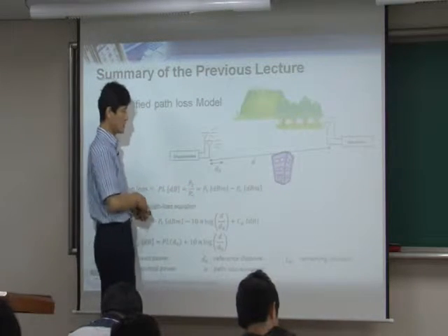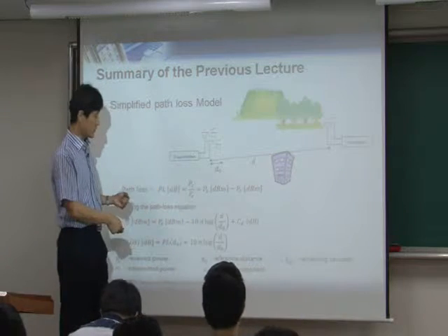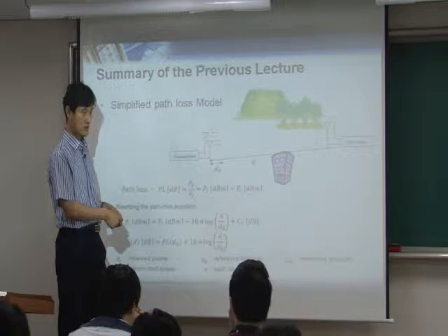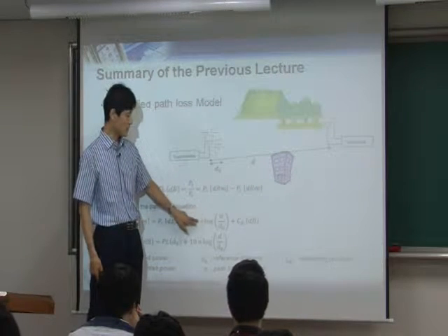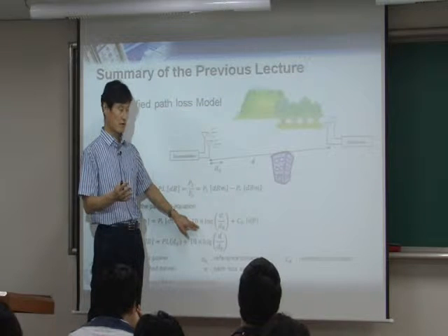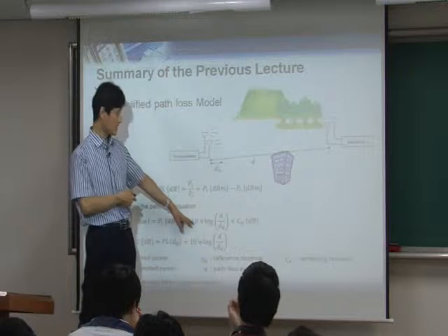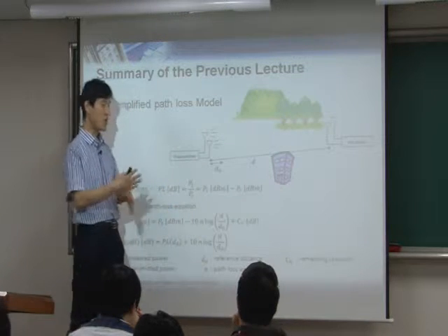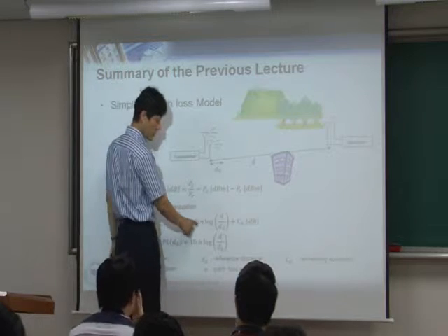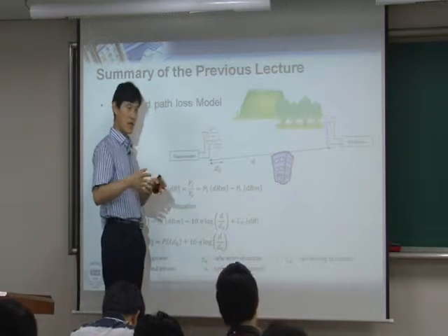The thing is, one of the goals is to measure this power exponent, or path loss exponent. This path loss exponent, again, varies depending on the environment. We'll give you an example on the next slide, but this one changes based on the environment. So in order to find out what my path loss exponent is in my environment,